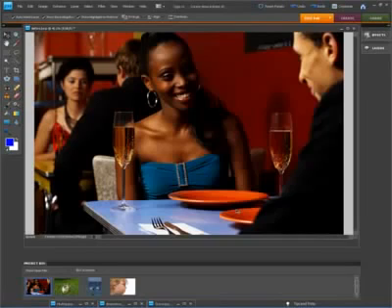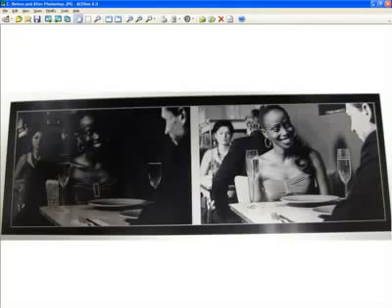I've recently engraved this exact graphic, and then I modified it through Photoshop, and then I engraved it again as well. Actually, I engraved them both at the same time. If I click on the graphic that I engraved, this is a photograph of anodized aluminum. On the left side was as is. I did nothing to the graphic. It was very dark, and I engraved it as is. On the right side, I modified it through Photoshop, and I engraved both of these at the same time, same settings. So there was no difference in power, speeds, or laser settings whatsoever.